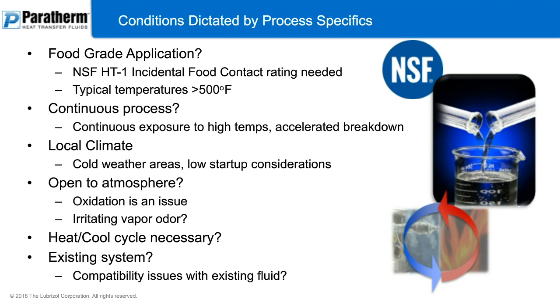And is this an existing system that's already been in operation? This might be the most important condition that's going to dictate what you're doing. An existing system will have existing fluid in it. You're changing that fluid for a reason. Maybe it didn't meet your capabilities. Maybe it broke down. There's a lot of degradation. There's some fouling that was happening in the system.